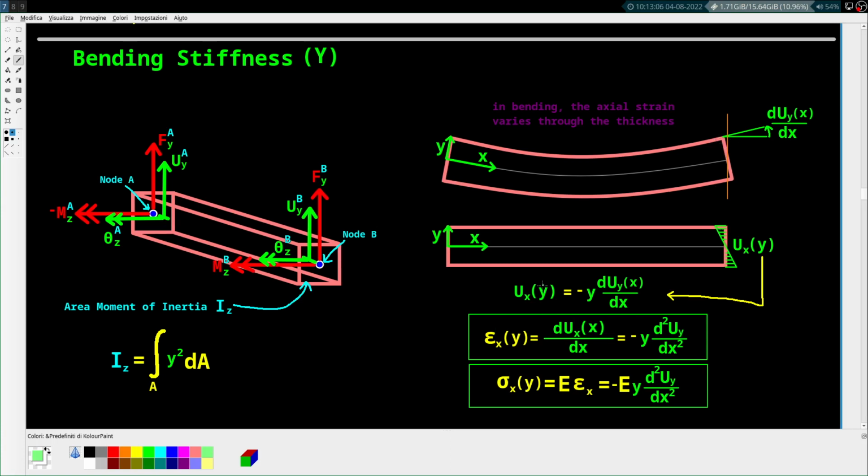And if you multiply it by the distance from this neutral axis y, you can actually compute how much you're actually moving in throughout the thickness, right? And so if, let's say this was a 2-inch thick part, at y equals 1, you would have a negative, whatever the slope is, that's your axial displacement here. Whereas if you put in negative 1, that would be a positive displacement, right? Obviously because this is to the right and this is to the left.